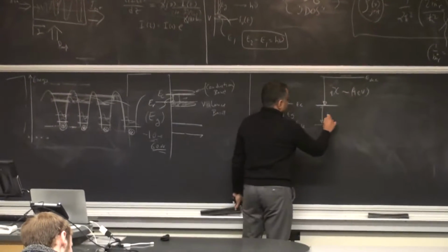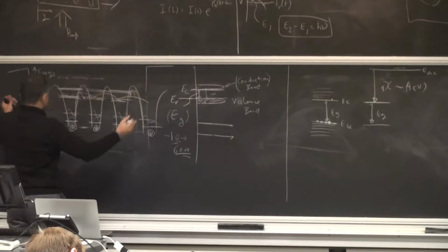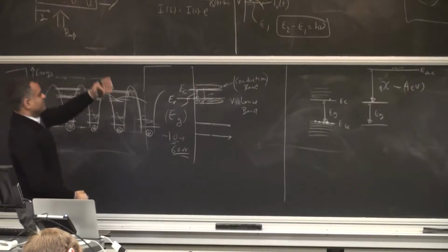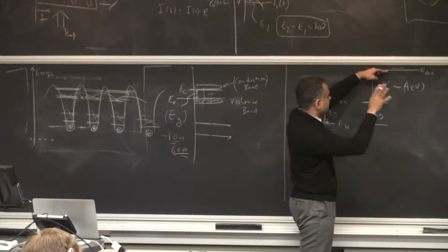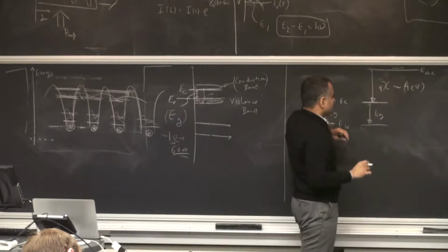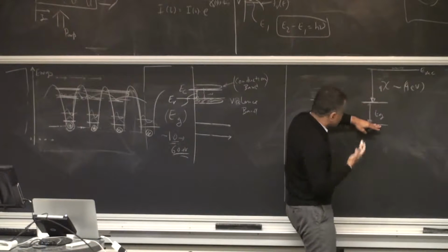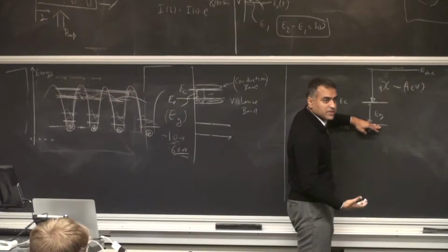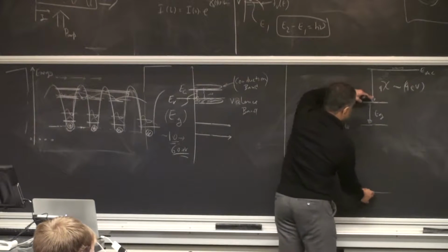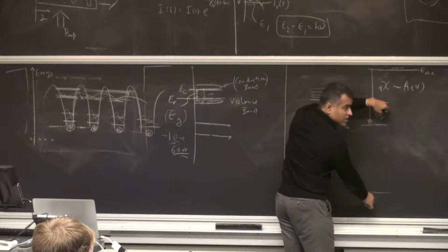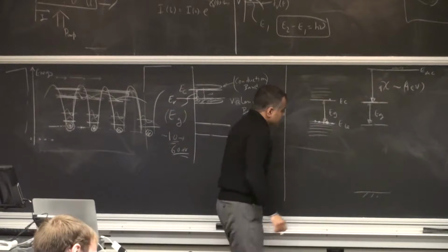But the band gap is the more important quantity here. Just to locate ourselves, where in energy are we? In the conduction band minima, we are about 4 eV above the free electron, when the electron is not bound to the crystal at all. And if you're in the valence band, you are a further band gap below it. So for example, in a very wide band gap semiconductor like 6 eV, you are almost 10 eV below the vacuum level. That electron is very hard to pull out.